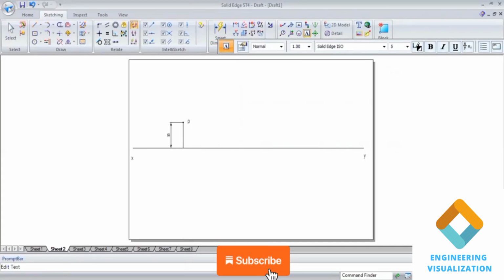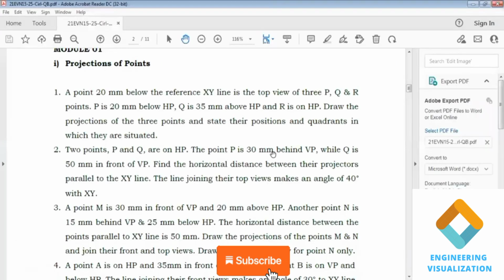Okay, now in the question they have mentioned one condition. The top views are joined with a line at an angle of 40 degree. You can see that the line joining their top views makes an angle of 40 degree with XY. So I will first draw this 40 degree angle line from this top view.